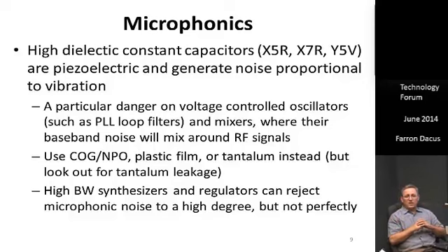So allowing that dynamic range means that you typically have to work down to the noise floor, and I mean the thermal noise floor. You don't want a lot of other things degrading that noise floor, and in a high vibration environment, say on an aircraft, that can easily happen, that the jet turbine vibration will shake these capacitors and generate a lot of noise at the turbine spin rate.